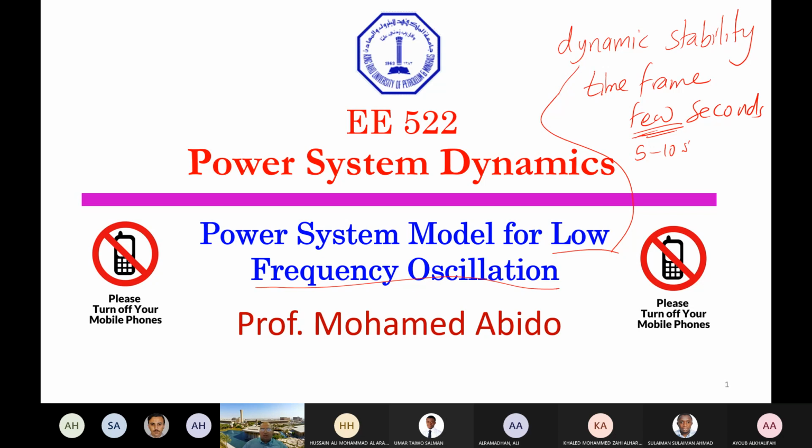In transient stability, in a few milliseconds, the exciter system will not be able to provide any damping, since it is slower than this. But in 5 to 10 seconds, you allow the exciter to provide a damping signal to improve the system stability.